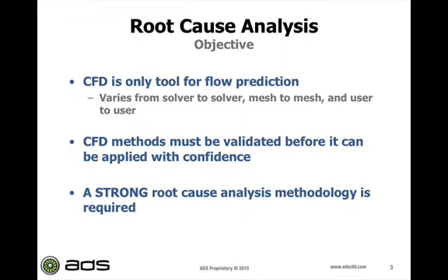Second, if you want to use CFD as a design tool, the CFD method must be validated before it can be used. I want to emphasize validation instead of calibration. We'd like to validate the methods, and to validate methods, a strong root cause analysis method is really required to achieve that goal.